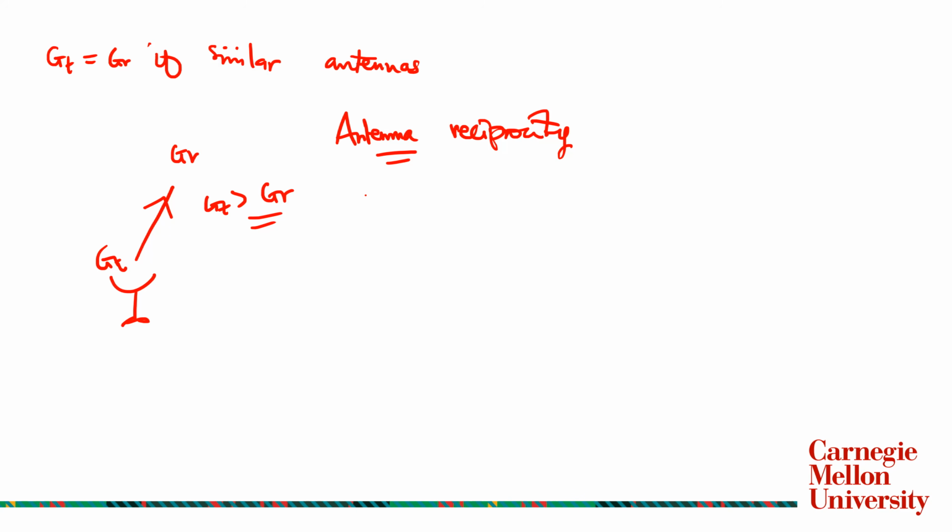If we know what power we should receive, which is the threshold, say my threshold is maybe negative 150 dB, and these are the antennas I have, how much power should I transmit? So you can also work backwards towards setting the transmission parameters.